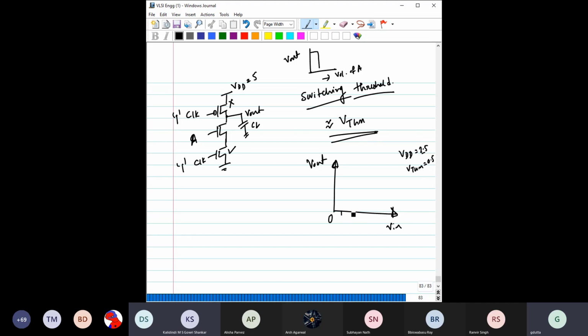So this, 0.5, 1.5 to 2.5. And here also, say 1, 2 means 1 volt, 1.5 to 2.5. Okay, and say the voltage level is here. So around this 0.5 it will start falling, right? From this, can you comment on the noise margin? Please comment on the noise margin from this plot.